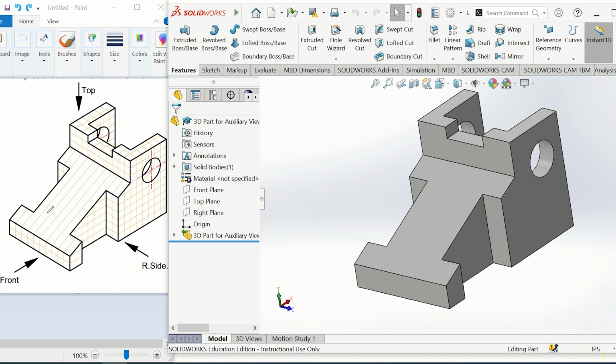If I look at this surface from the front view, I would see distorted dimensions of this eye shape. It's going to look shorter than what it actually is. If I look at the right side, at this eye-shaped inclined surface, of course it's going to look like a straight, inclined line, something like this. So this line here is going to be projected to the front, and these two lines here and here remain the same.